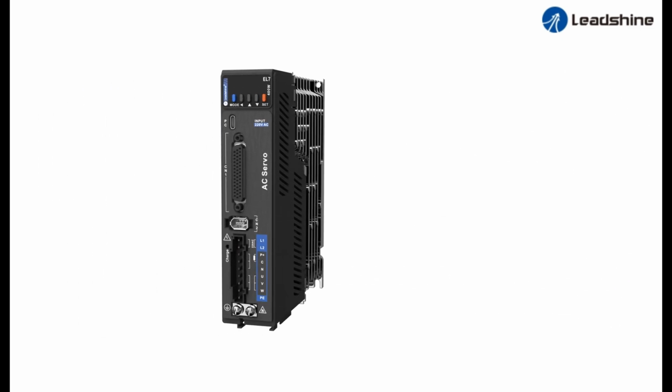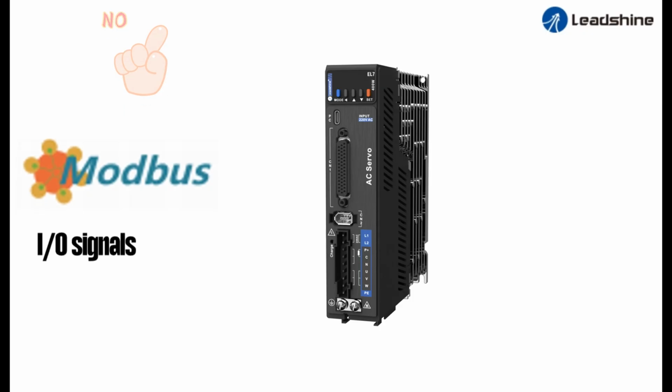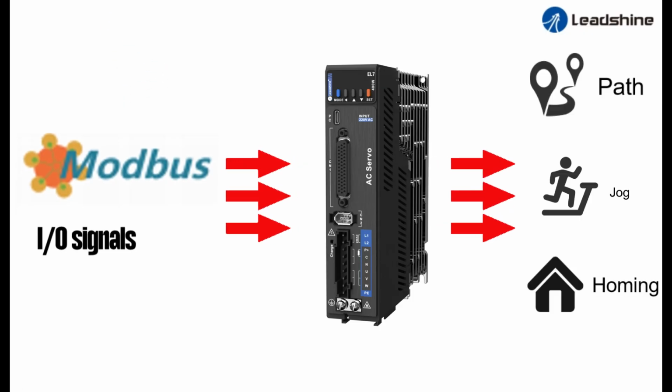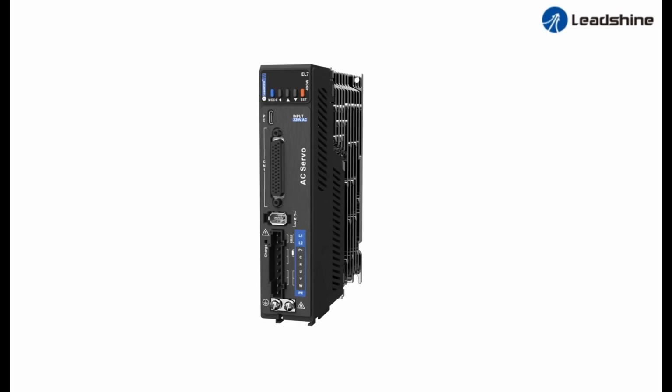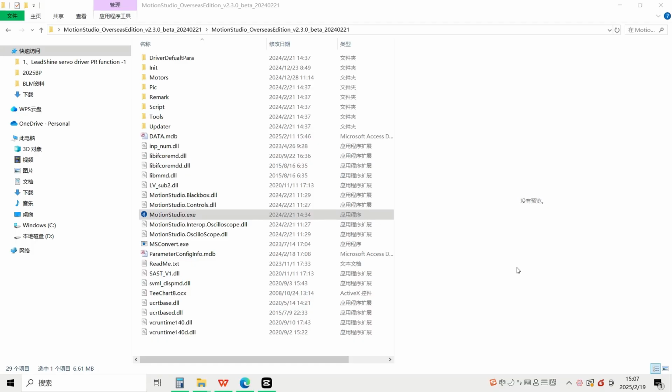In the PR mode, the drive can locate the accurate position by itself, without a high-cost location module or motion controller. General I/O signals or Modbus communication can trigger the accurate positions or other movements. PR functions will save resources on the main controller and reduce the equipment cost. Now let me introduce the PR function.